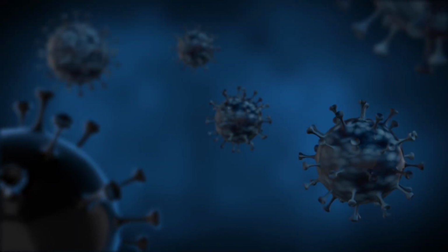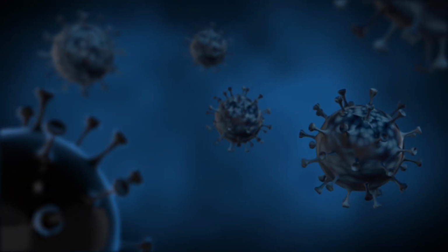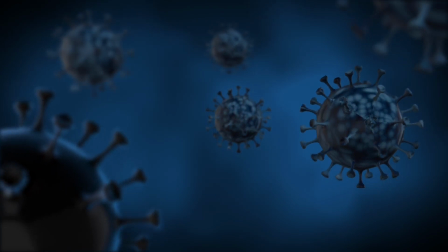An activated carbon air filter consists of a bed of carbon encased in a mesh-like material. These filters remove gaseous compounds from the air. Molecules such as odors and volatile organic compounds, or VOCs, are very small and will slip through your standard air filter. Activated carbon filters trap these molecules and remove them from the air in your building.